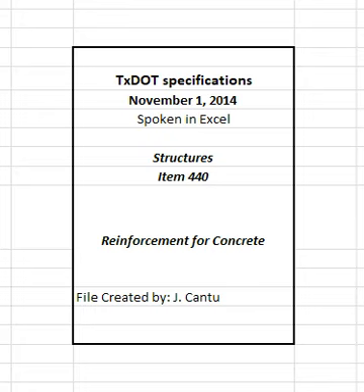Table 2. Wire size number, diameter, and area. See table in specifications. Note size numbers, inches, are the nominal cross-sectional area of the wire in hundredths of a square inch. Fractional sizes between the sizes listed above are also available and acceptable for use. 2.7 Epoxy coating. Provide epoxy-coated reinforcing steel as shown on the plans. Before furnishing epoxy-coated reinforcing steel, an epoxy applicator must be pre-approved in accordance with DMS 7330, Qualification Procedure for Reinforcing Steel Epoxy Coating Applicators.